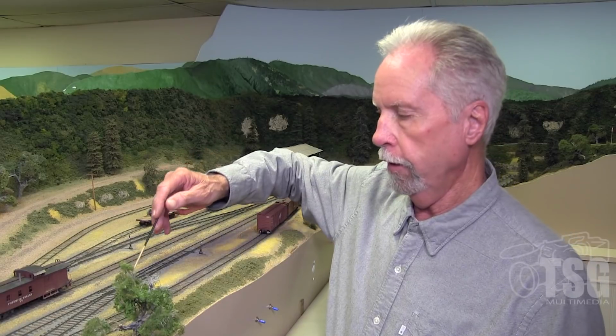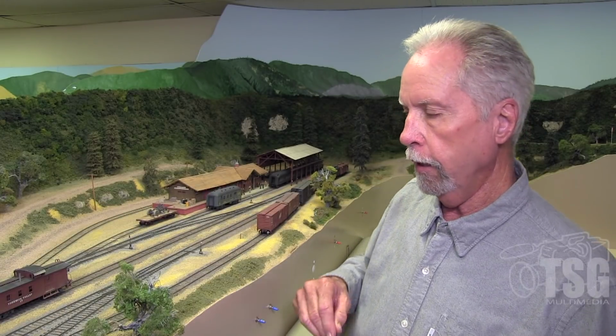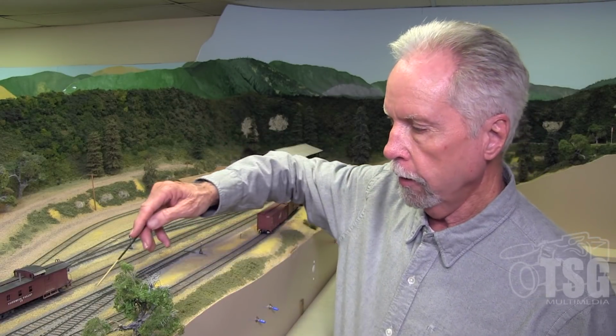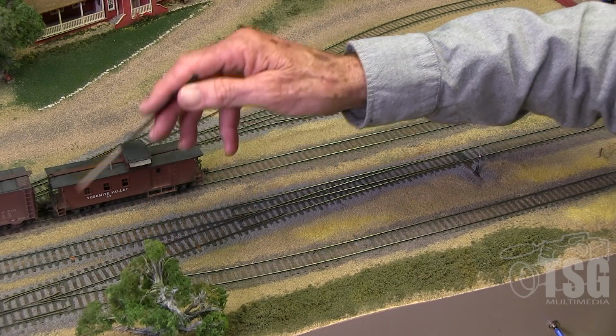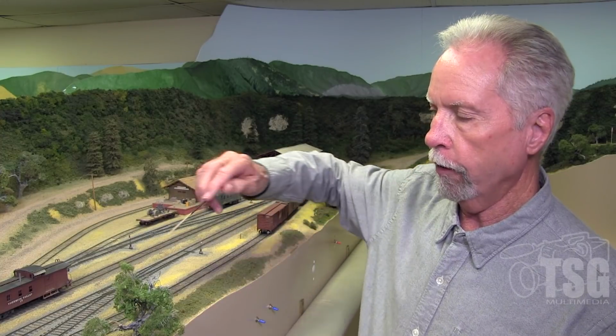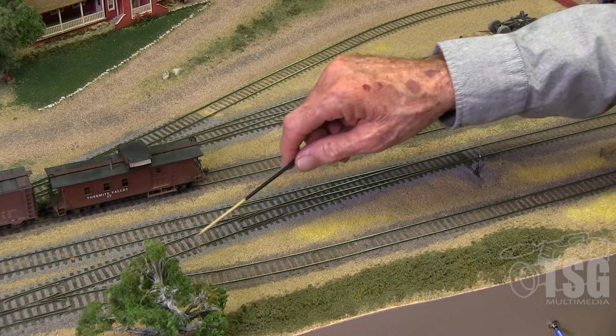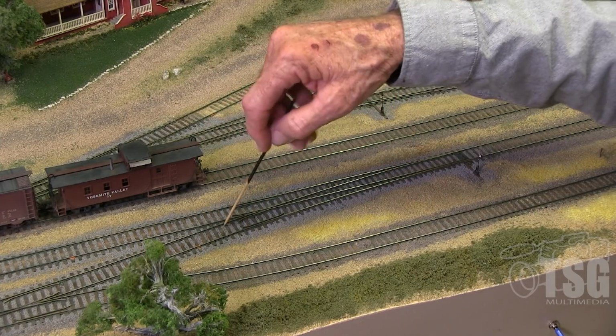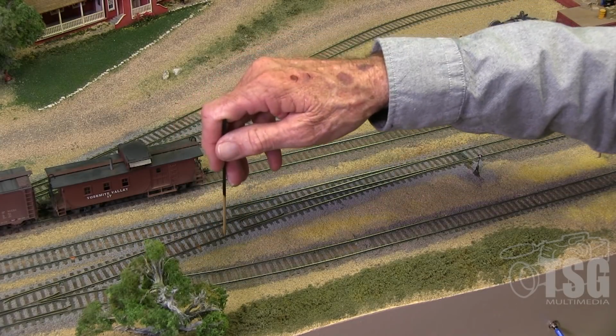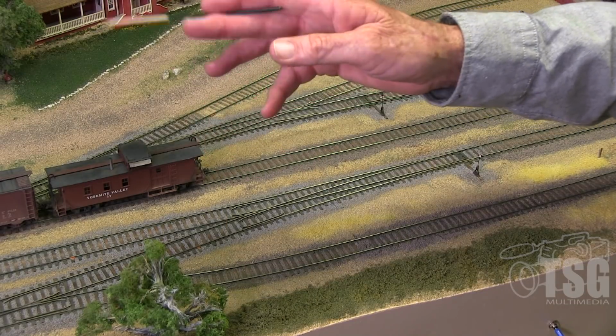Another thing I learned after I got command control and my operators were more experienced: on the rest of the layout, I might have the gaps for that frog maybe way up here. It didn't make any difference. Well, now with command control and people more knowledgeable, I have to warn operators, if you want to come in and drop your head brakeman off to throw the switch, you've got to watch where this frog is or where the gaps are, because if you cross the gaps without throwing the switch, you're going to short out.